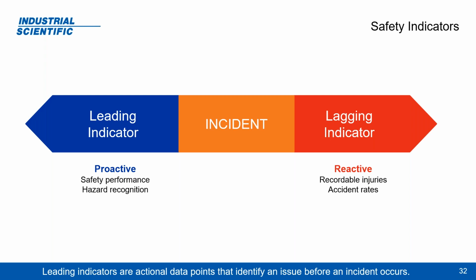No, we didn't get anything from these gas detectors related to this incident, but the gas detectors weren't bump tested before they were being used, and they haven't been calibrated for the last 3 months or last 6 months or whatever the case may be.